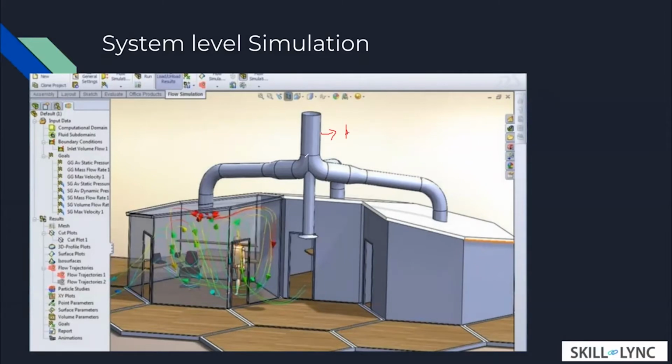And you have these ducts which basically take air through different channels, and it's basically sending air to each and every room. So what you can do is, if you solve the mass equation, the continuity equation, the momentum equation, the energy equation, and the turbulence equations, which is called the turbulence model, then you will be able to predict accurately, if your mesh is correct, what is the temperature and what is the temperature distribution and what is the temperature disparity in the room. So these are some things which you can do very easily with simulations, and they're quite accurate.